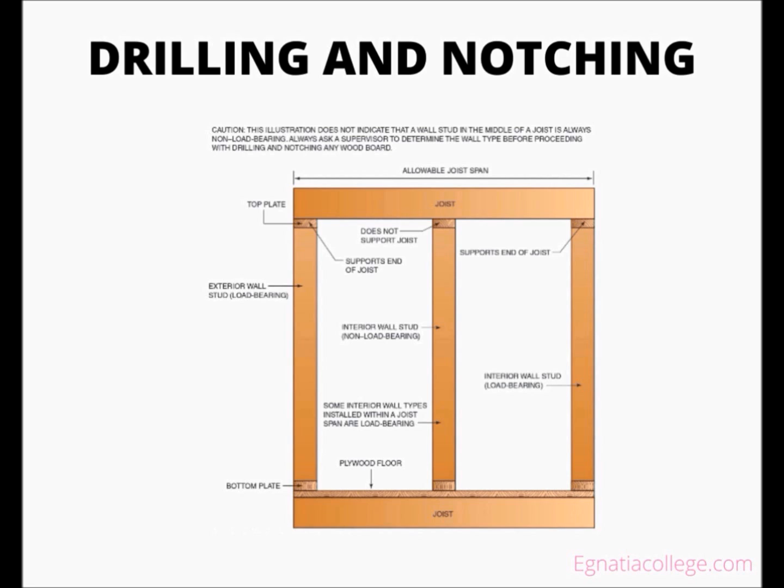Piping installed horizontally through a wall stud requires only a 1½ inch wide nail plate, but pipes passing vertically through a top or bottom plate must be protected with a 4 inch wide nail plate. Some local codes specify the kinds of nail plates that can be used. This information is listed in a local code book.